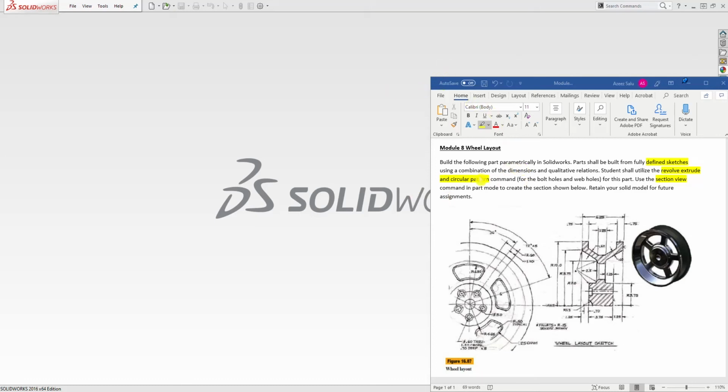In this tutorial we are going to be designing this wheel layout, and according to the instruction, your instructor wants you to create this part using a sketch that is fully defined. It wants you to use the revolve method, and it wants you to use the circular pattern to create the hole and this shape over here, this pattern. And at the end we are going to create a section view.